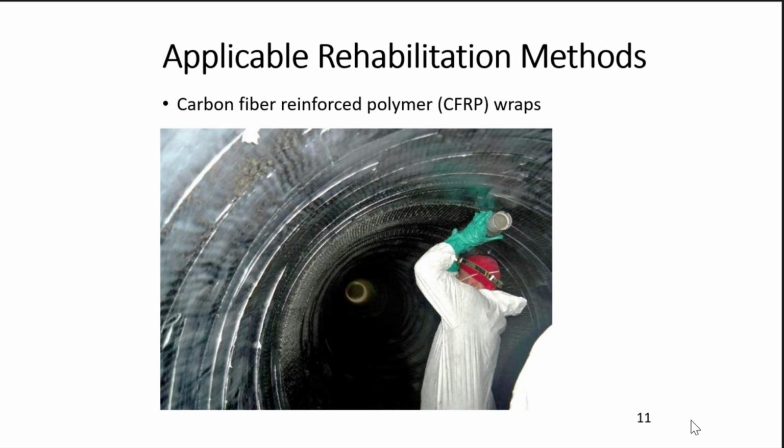safe working conditions. But if you can allow it, it kind of looks like wallpaper, just like putting, which I know wallpaper is not so common anymore, but putting wallpaper up, just applying your resin and then layering in the fibers, and you can run the fibers in multiple directions, and you can add quite a bit of strength. So this is more of a spot repair location, spot repair technology where you can go through a pipe and assess it.